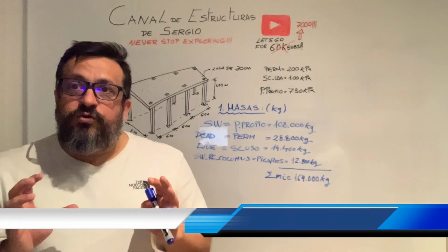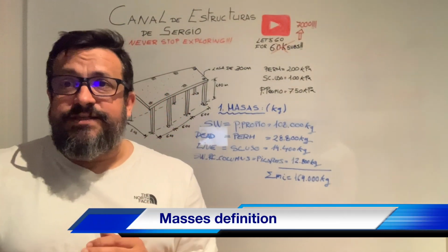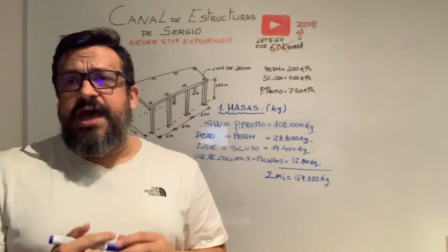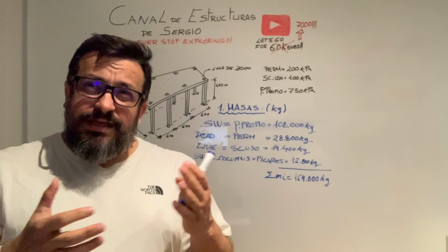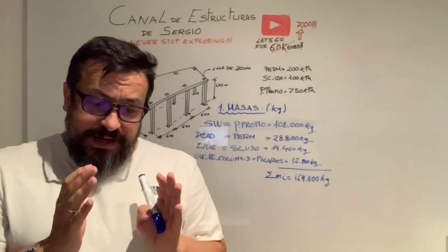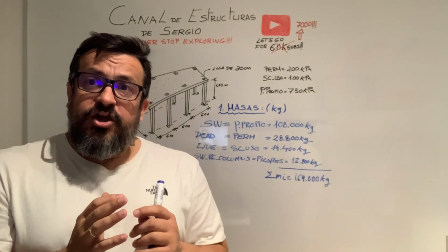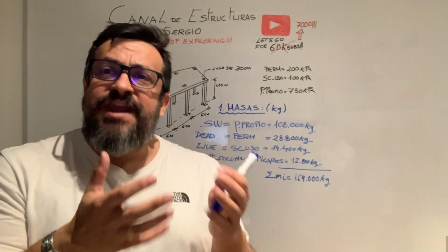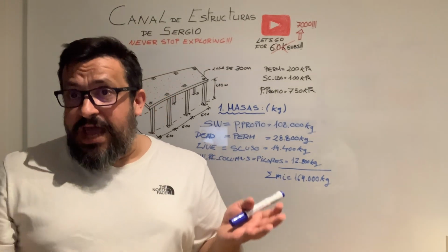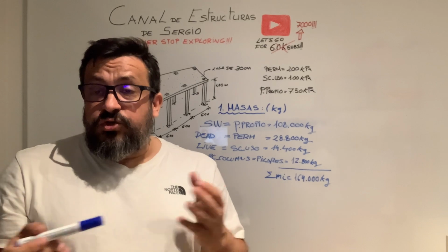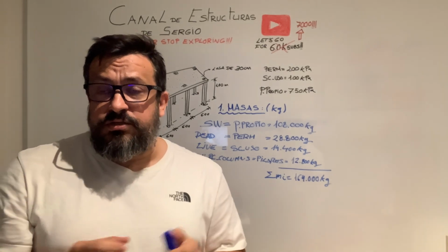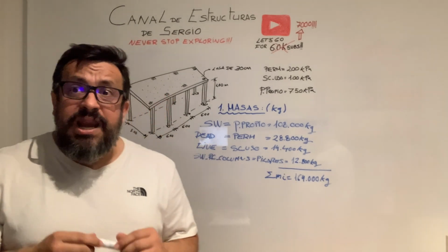The aim of the video today is to deduce the equivalent seismic forces acting against the structure. This is a particular simplified method to try to make it simple, compared to dynamic analysis, normally modal analysis. This methodology is also collected in many design codes. For example, in Eurocode 8 it is called the lateral force method.